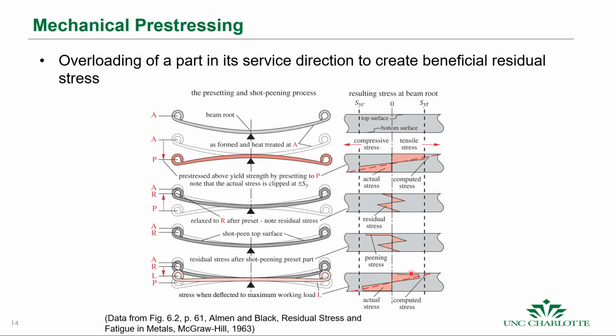So it's a pretty fascinating process for improving the life of these components. And these leaf springs can last forever, but they don't last forever just because you took some metal and bent it in. There's some pretty clever people that actually went through these processes, so that at the end of the day we have these desirable stresses at the surface. So this is just an example of some of the options that you have to improve fatigue life.